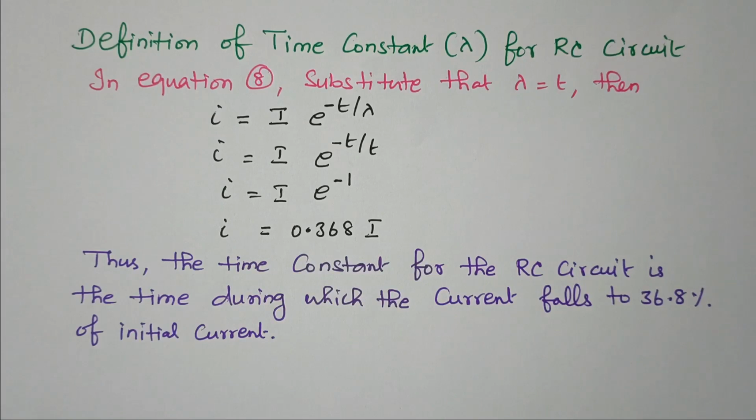So in this video we discussed the DC transient response of RC circuit, resistor capacitor, charging, case 1. Charging, discharging available in separate video. We analyzed the current i of t, that is decreasing in nature. Then we analyzed ER and EC also. ER is decreasing but EC is increasing. Finally we calculated the time constant also.